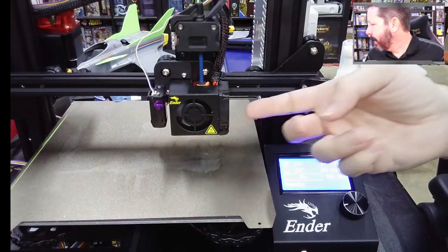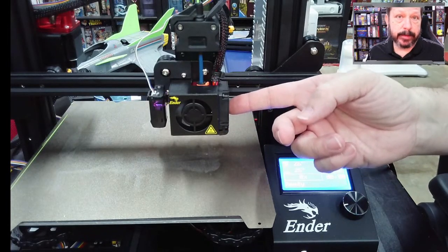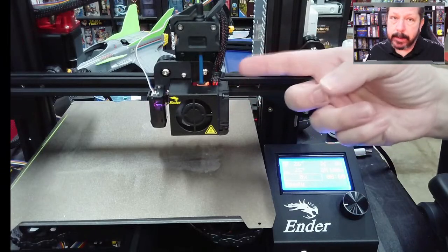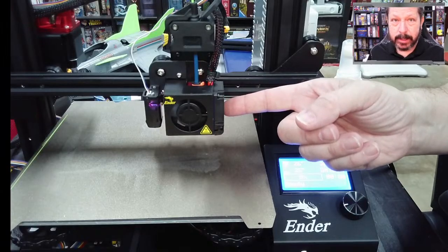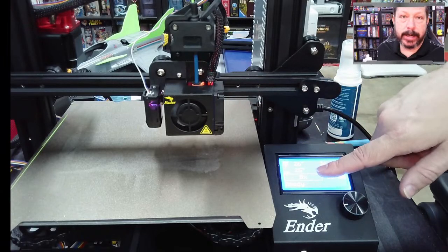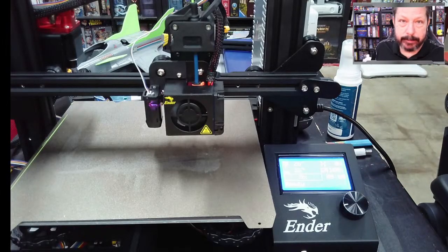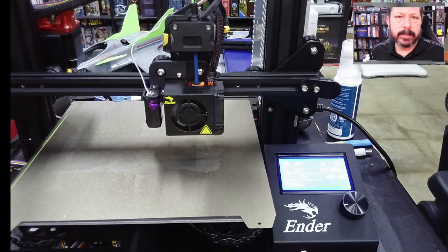So the fan on the side, this one, can be off, and it will be off. Typically slicers have this one off on the first layer no matter what print you're doing. So I would go to the menu here and try to turn it on manually and make sure it still functions, because it could just be that you only looked at the first layer.